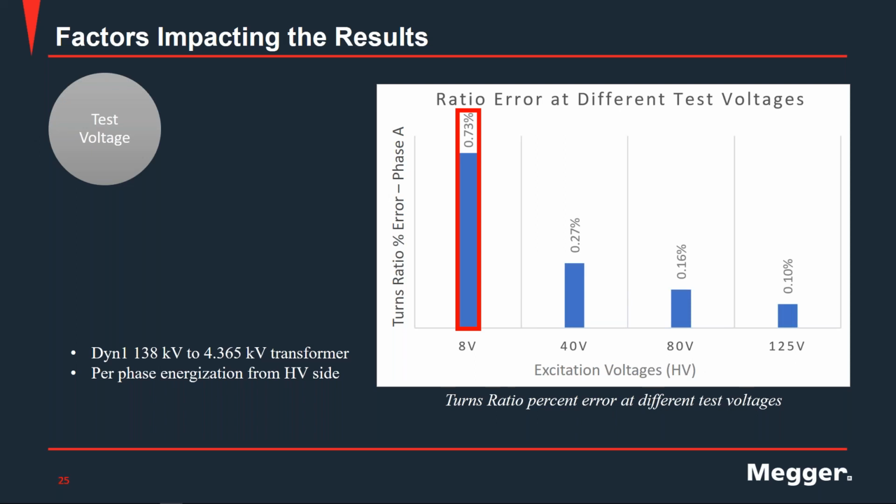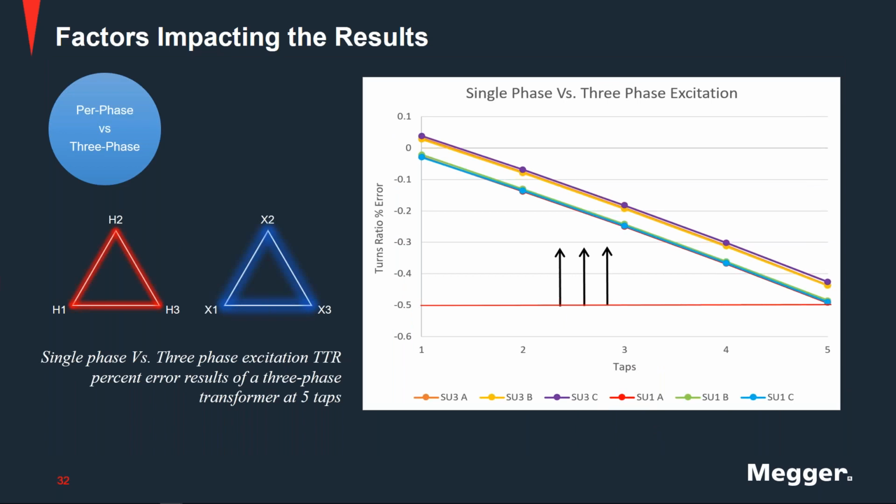And also, going back to Ken's points during the presentation, doing single-phase versus three-phase excitation is important, as three-phase excitation on a three-phase transformer will be a more accurate measurement.